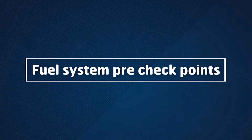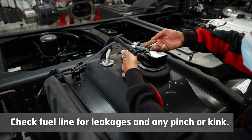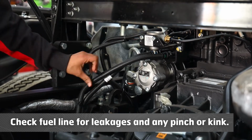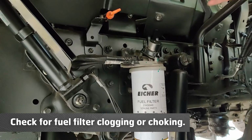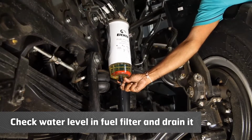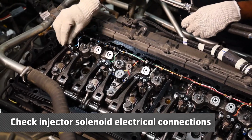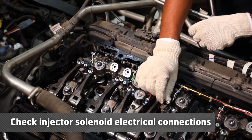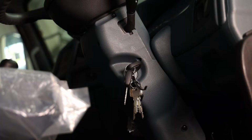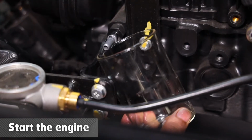Fuel system pre-check points: check fuel level in the tank, check fuel line for leakages and any pinch or kink, check for fuel filter clogging or choking, check injector solenoid electrical connections, start the engine and check the fuel return line to verify fuel is coming out or not.